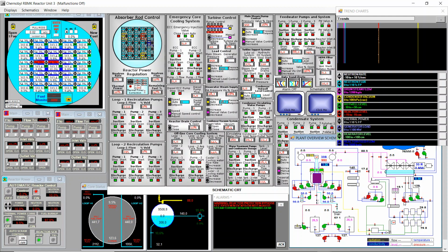So one out of the 3 pumps is on, and this pumps the water from the hot well that comes after the condenser. The condenser is fed by one of the 2 pumps, which is on, the other one is off. And overall, all the system at this moment is like in a startup procedure. The turbine is not connected, it's in turning gear.